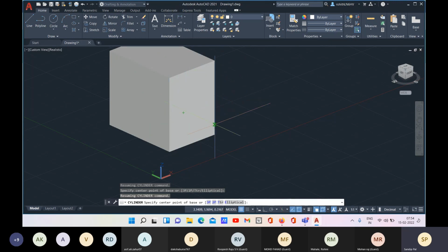We have this box and we can do it. So for that, just F6 is there, and you see it is highlighting. When I'm placing my mouse pointer on this surface, it is getting highlighted. So that means this one is your working plane. For your temporary purpose, this plane is your working plane right now. So that is your dynamic UCS. Your UCS will work dynamically.